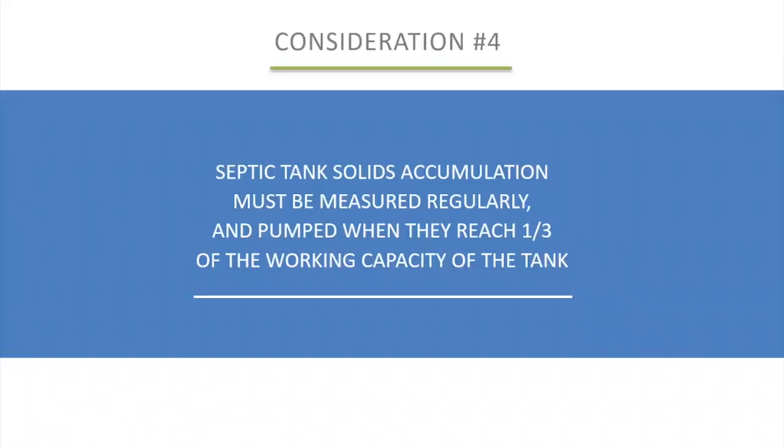So you have to be very cautious with where you build, and that's why we have lateral separation distances between the final receiving body and where the water would enter the environment. Septic tank solids accumulation must be measured regularly and pumped when they reach 1/3 of the working capacity of the tank. So it's a measurement.